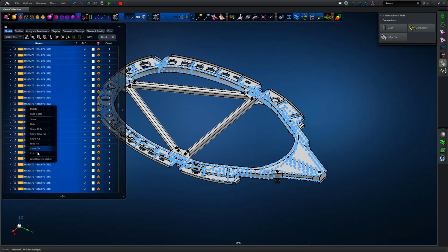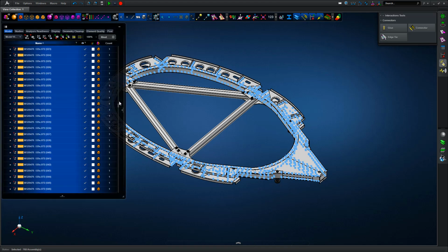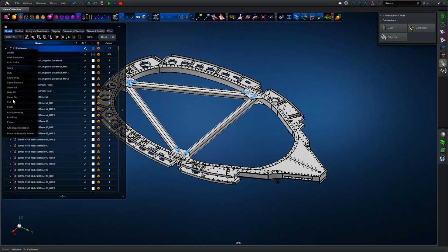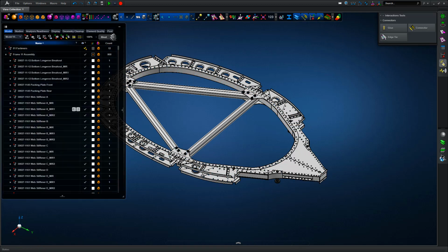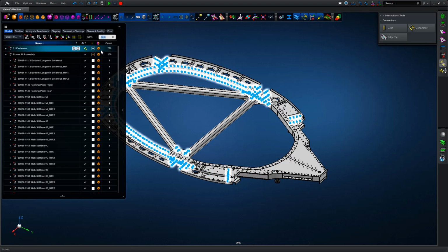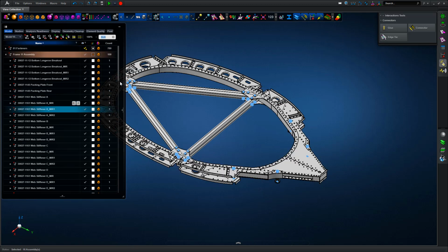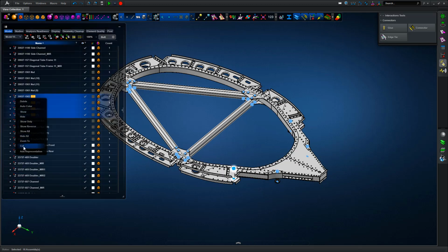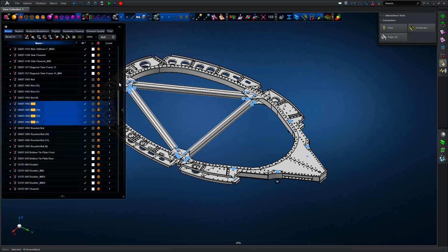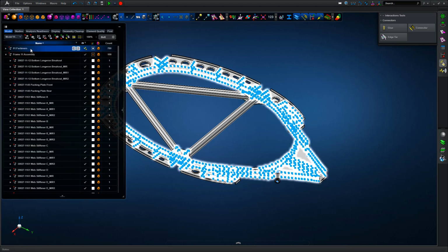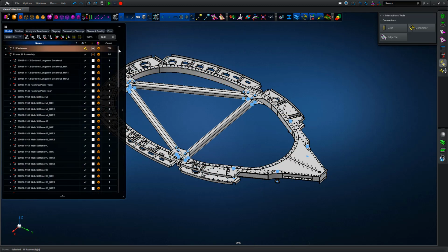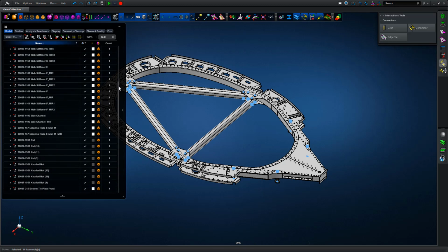So we're going to repeat this. We've now got rivets, so we can again highlight them with the search term, cut them out of the main structural assembly and then paste them into the fastener assembly, and we'll repeat that for the remaining fastener entities. We've got bolts and other fasteners in there which we can just cut out and move into the fastener assembly. So just a simple way of simplifying the overall sub-assembly.